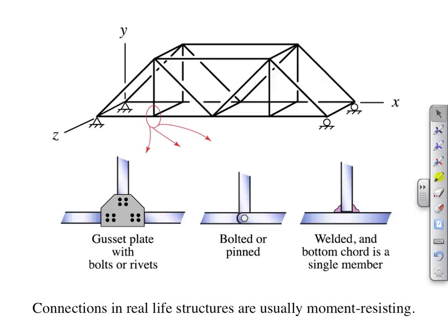The important point, however, is that a two-force member only transmits force along a line of action connecting its two pinned ends. A common application of truss analysis is bridges, and we see a perspective view of one such truss here. The actual connections between members in bridges are far more rigid than is implied by our treatment of trusses as assemblies of two-force members. Gusset plates can have hundreds of rivets in a single connection. This means the actual connections between members have the ability to react moments, which is in violation of our treatment of the assembly as a set of two-force members. Nevertheless, the actual axial loads carried by members of the assembly are well approximated by treating the assembly as a set of two-force members, and we will use that approximation independent of the actual connections between members.